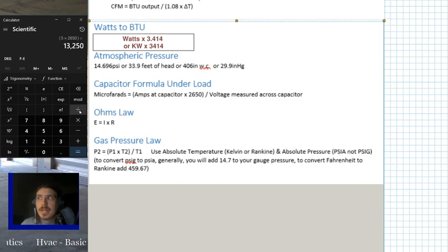And we're going to divide that by a realistic voltage you might get. Remember, capacitors are rated for 370 and 440 volts. The reason they're rated for those voltages is because you actually see them. So a realistic voltage here might be 345. That would be a 38 microfarad capacitor. So those are two relatively realistic readings.